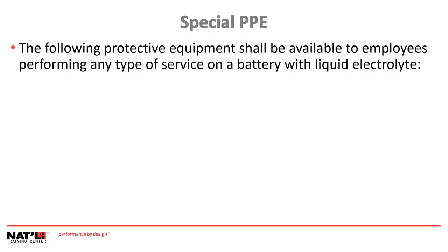PPE shall provide protection from electrical hazards. PPE shall include one or more of the following, as determined by project management: footwear, gloves, sleeves for wet service, footwear, gloves, or sleeves for dry service, electrically insulated head protection, protective clothing, eye protection with non-conductive frames, face shields such as polycarbonate or similar non-melting type, preferably arc rated.